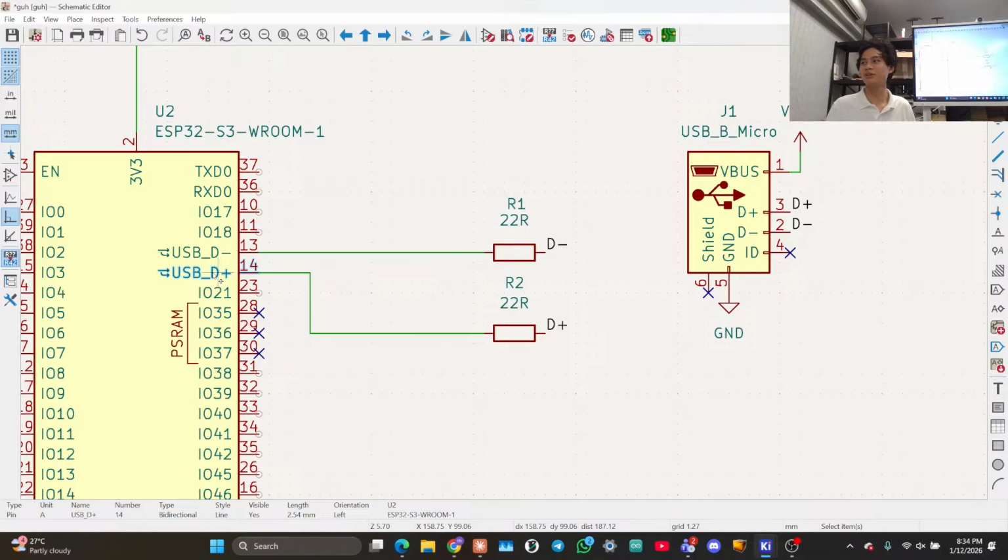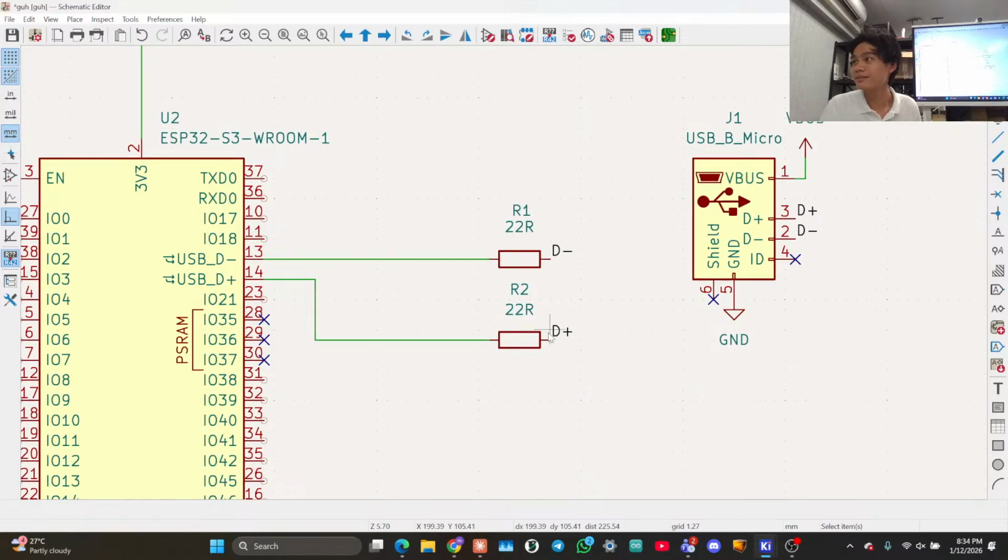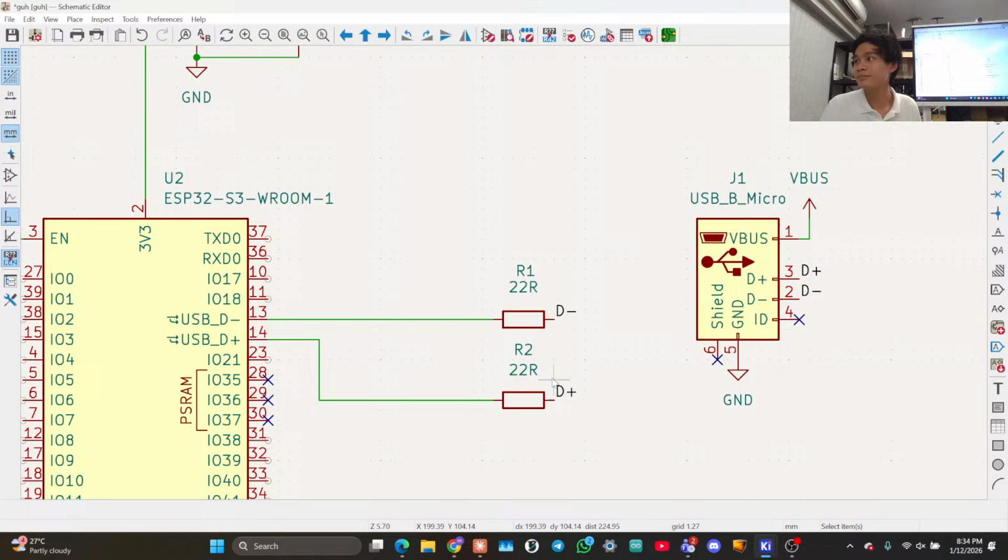Why are you looking at me so disapprovingly? Moving on. It isn't necessary if you do the impedance matching correctly. Those are more like a production bodge. So I've been production bodging all my own boards. USB lines should be short enough that it doesn't really matter, but still. My USB lines are very short, so it's fine. You shouldn't use the impedance calculator yet. That is in future lessons.